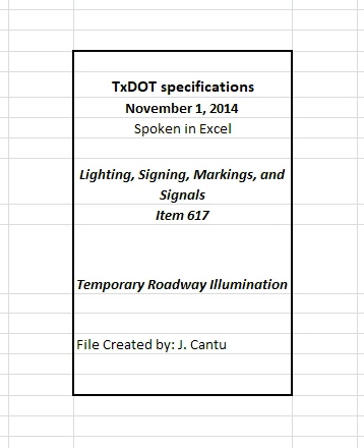3. Construction. Perform work in accordance with the details shown on the plans, the NEC, the NESC, and the requirements of this item. Use established industry and utility safety practices when installing, relocating, or removing electrical and lighting equipment located near overhead or underground utilities. Consult with the appropriate utility before beginning work. Tension and sag overhead conductors with guys and anchors in accordance with utility distribution practices.